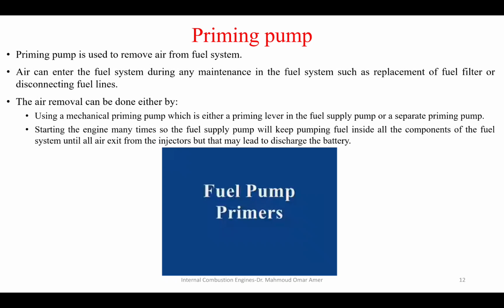Priming can be performed through two main ways. The first one is by using a mechanical priming pump, which is usually with a lever that you keep pressing until you remove all the air from the system.